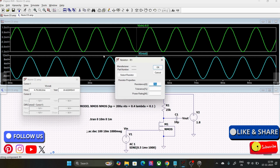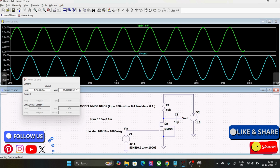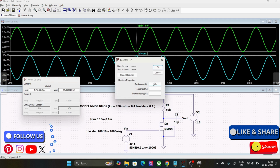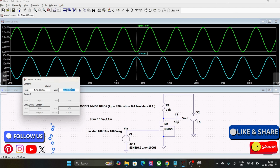From 25k, if I increase it to 50k, the gain should increase, so let me run it. You see from 10 it jumped to 20, so it is almost increasing by 2. If I increase the value of RD from 50k to maybe 75k, we again expect the gain to increase. Yeah, the gain is right now around 26.